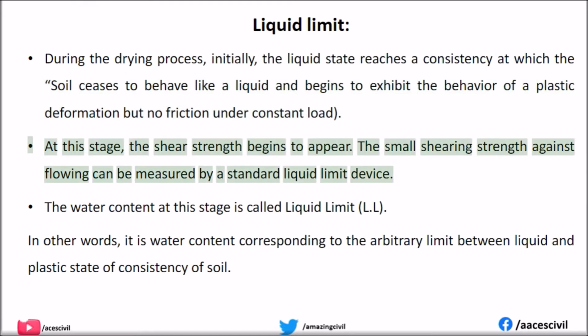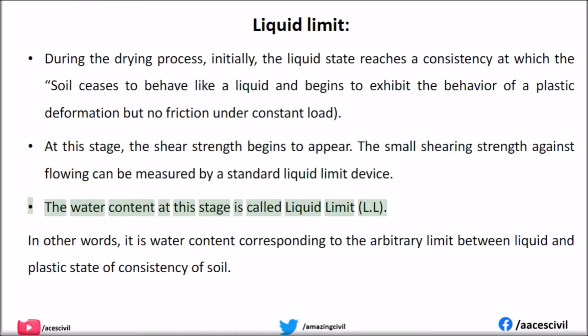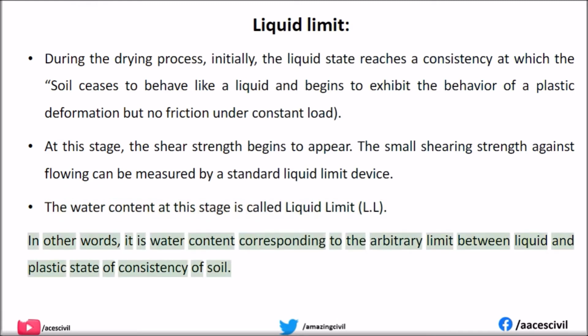At this stage, the shear strength begins to appear. The small shearing strength against flowing can be measured by a standard liquid limit device. The water content at this stage is called liquid limit, LL. In other words, it is the water content corresponding to the arbitrary limit between liquid and plastic state of consistency of soil.